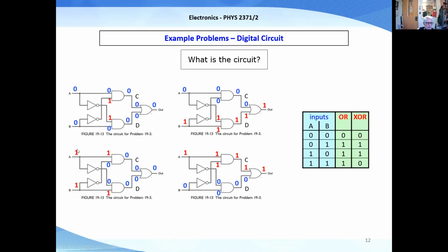And then you can do the final one. If you have 2 1s coming in, you're going to get a 0 out. Okay. You have symmetry here and symmetry here because you have a 1 and a 1, and you also have symmetry of all the parts. You have sort of physical symmetry with the parts, and the 1s also have symmetry, mirror symmetry. Okay, so what you get out of this circuit is an exclusive OR.